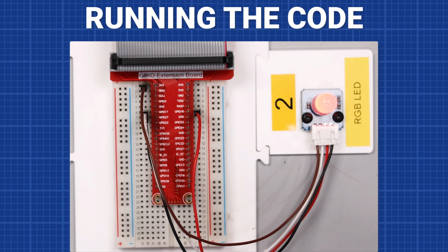In this lab, we demonstrated how PWM allows us to control the brightness of an LED. In future labs, we'll explore controlling the green and blue LEDs, even creating more complex light patterns. Feel free to experiment with different duty cycles to see how it changes the brightness.